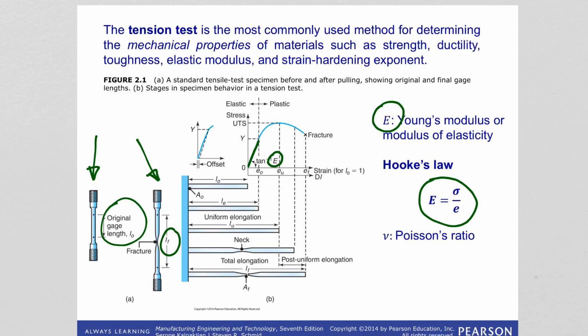When we reach the yield strength, shown here with Y, permanent or plastic deformation occurs. For soft and ductile materials, it is not an easy determination where the linear region changes to the non-linear region, so it is not easy to determine the yield strength.